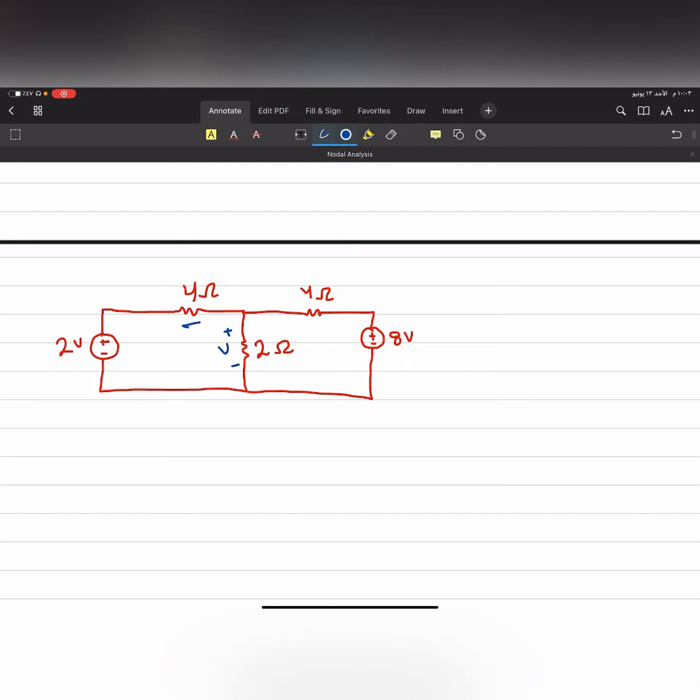So in this case, you have to do the nodal analysis. You have to understand, guys, that this node is the ground. Why did I say that this node is the ground? Because it has the most branches. Here it has 1, 2, 3. You can also say that this node will be the ground because it has 1, 2, 3 branches. I will say that you are correct.